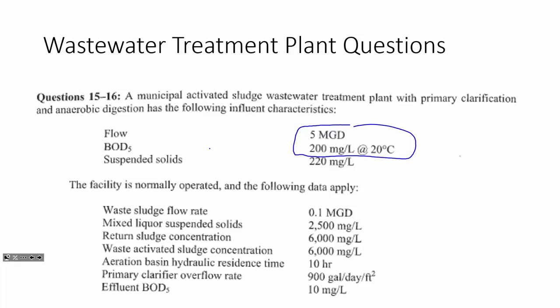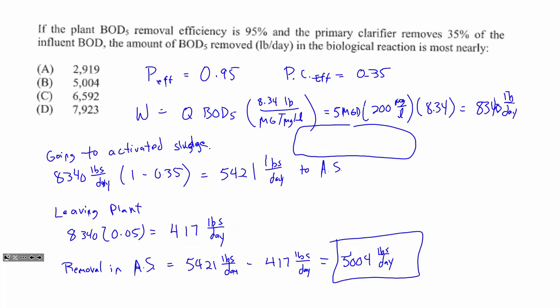And we know what the flow is coming through that basin. So if we know the flow and the residence time, we can determine what the volume of that basin is going to be. This is pretty much just using the flow rate identity in this problem.